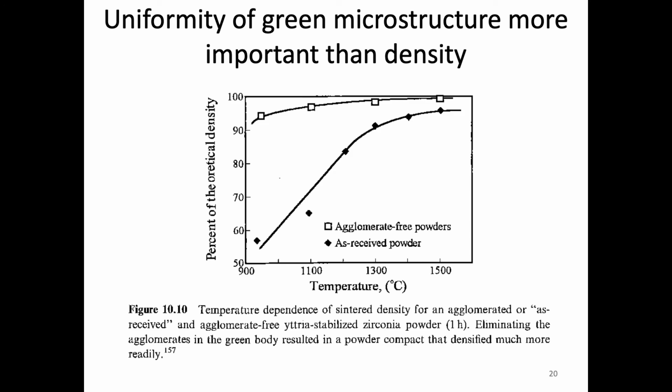Okay, another factor that goes into densification is the uniformity of the green microstructure. So we can't just say everything's the same when it comes to the powder compact or the green microstructure. The more uniform it is, the better.